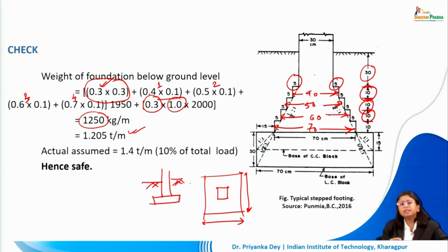So definitely a process very similar to what we've already undertaken will be used. The difference is, in that case, you wouldn't have to deal with the masonry offsets. We would not be proportioning the transfer of the load through various masonry offsets. We are directly making our column rest on a concrete base. So with that, we are ending the numerical, and I hope you have been able to develop a basic understanding of how to calculate the footings.